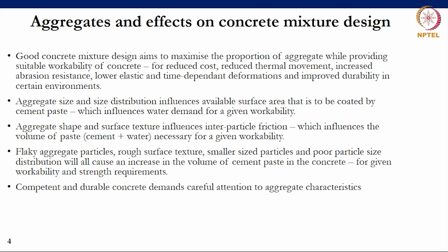Aggregate size and distribution influences the available surface area that is to be coated by cement paste. And this is an important consideration because it influences the water demand for a given workability of concrete. Aggregate shape and surface texture influence the interparticle friction during mixing and placing of concrete. And this influences the volume of the paste, that is the cement and water, that is necessary for a given workability.